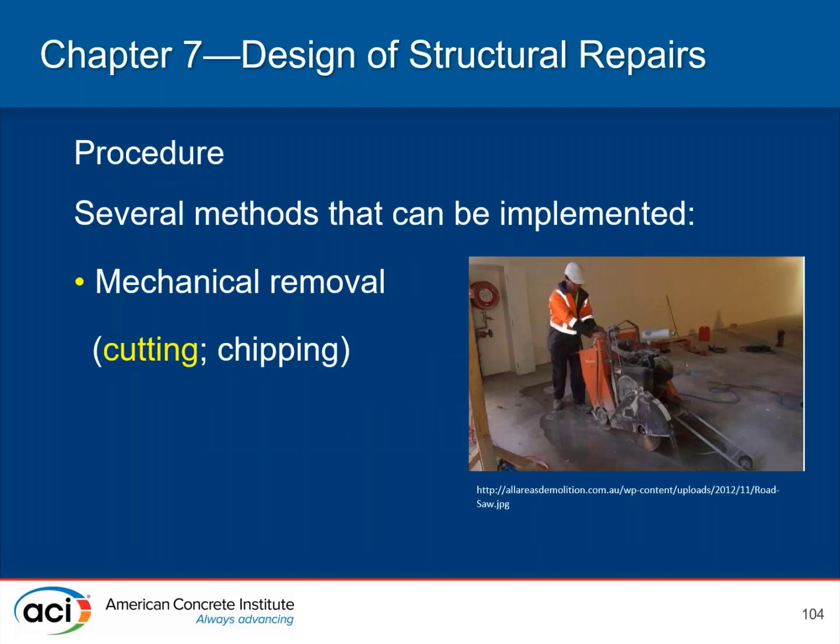There are a variety of different methods that are used for removal, starting off with cutting. Cutting around the repair area is important. It's critically important that the reinforcing steel is not cut when the concrete is being cut. So oftentimes our requirement is to ensure that you're at least a 1/4 inch away from the cover of the steel, so that you do not cut through any reinforcing steel that is a necessity for the structure.